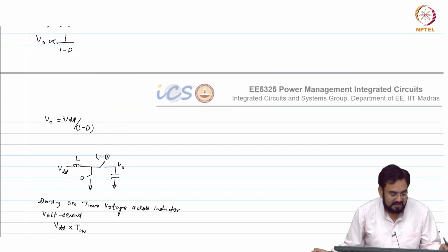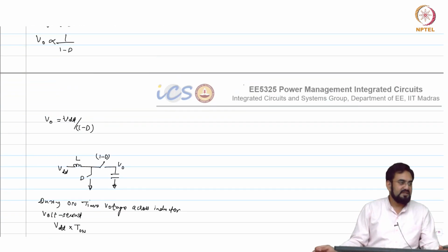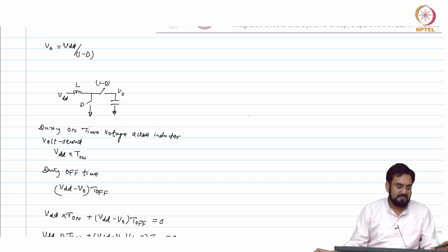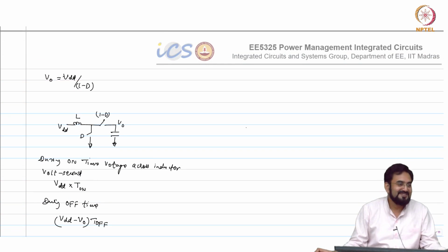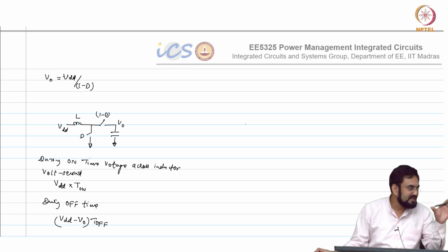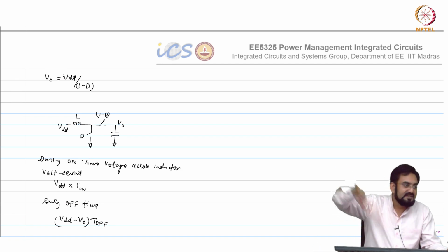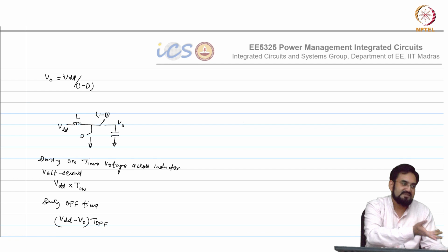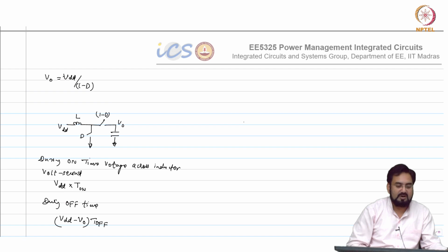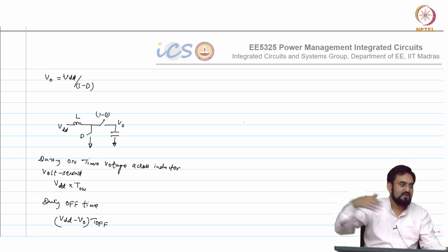Okay, so I will not go into detail about the controller and everything. But I will just briefly tell you there is one problem with this boost: it has a right half plane 0, just like you had in LDO. So, what does a right half plane 0 do? Gain is increased and phase response looks like a pole, while the gain remains the same as a 0. So, it makes it even worse actually, which means your output does not change in the fashion you want.